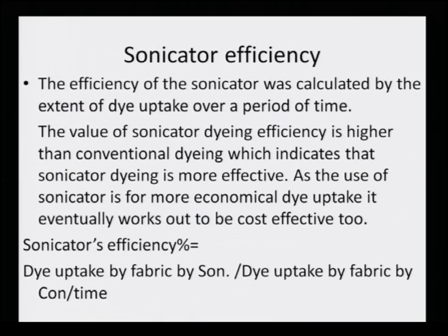As the use of Sonicator allows more economical dye uptake, it eventually works out to be cost effective too, because if the dye uptake is faster, the fabric will not need to be heated or boiled as long. In the conventional method it takes almost 3 to 6 hours, whereas with the Sonicator it takes only 1 to 3 hours. So, time saving is there, energy saving is there, and obviously money saving comes automatically. That is why it is not only cost effective, but one can even find out the Sonicator's efficiency percentage